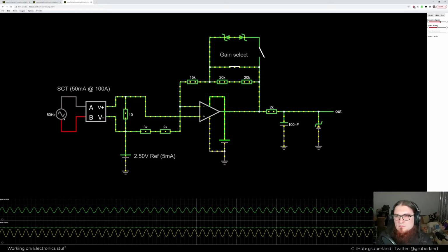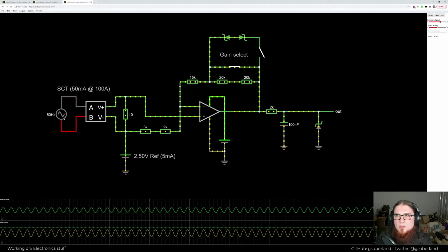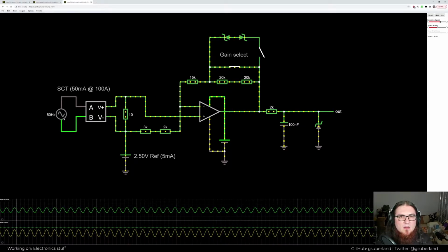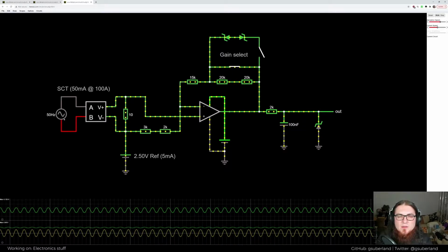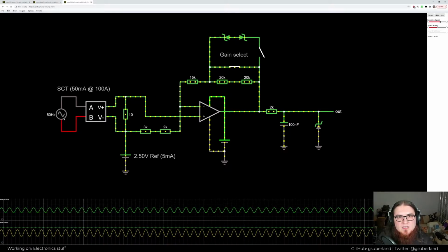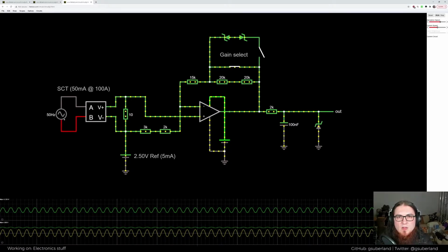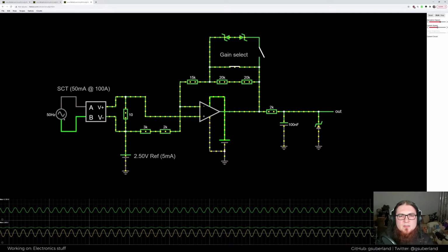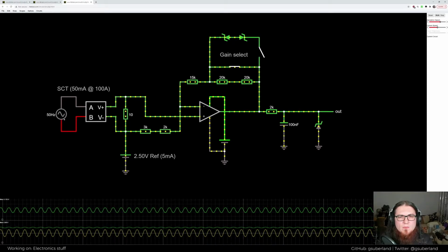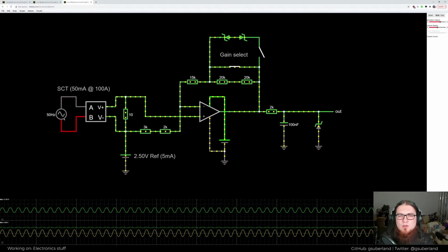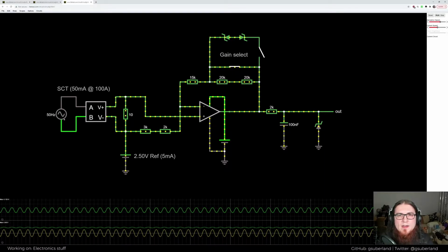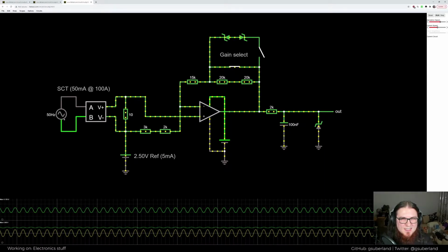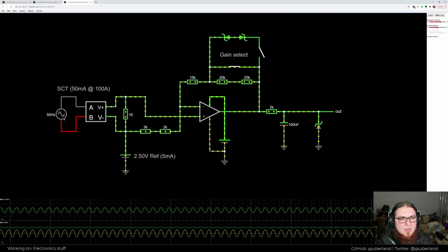Generally speaking, most of the circuits, in fact, all but possibly 1 or 2 of the circuits that I'm going to be measuring are limited to 32 amps by the breaker. And they're designed to not go above 32 amps. So 32 amps is just 1/3 of that total signal. So ideally, we would want to be thinking about using that full range for the 32 amp use case, instead of just 1/3 of the range.